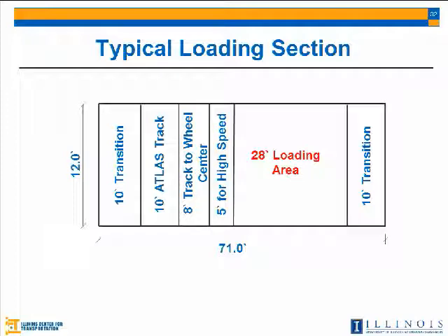Yes, we have the adhesive failure and we have the cohesive failure. And those two factors that you have mentioned, theoretically, both of them affect the moisture damage. We need to look at the type of aggregate that we are using, and also the type and amount of binder. Excess binder can lead to moisture damage. Also, a smaller amount of binder can lead to moisture damage.